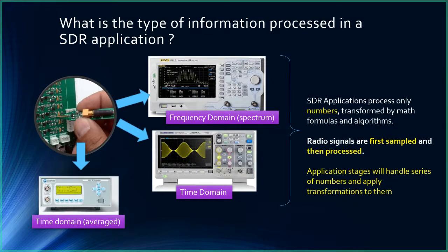Basically, the spectrum analyzer is plotting something in the frequency domain. What you see is a frequency and an intensity, while the oscilloscope is plotting an intensity and amplitude over time. Okay, so we are in time domain or in frequency domain. And in fact, the power meter is also plotting information in the time domain, but at a different speed, let's say. That's average. So basically, you take the same information from your circuit, from the probe, and what only changes is how you represent the same information.